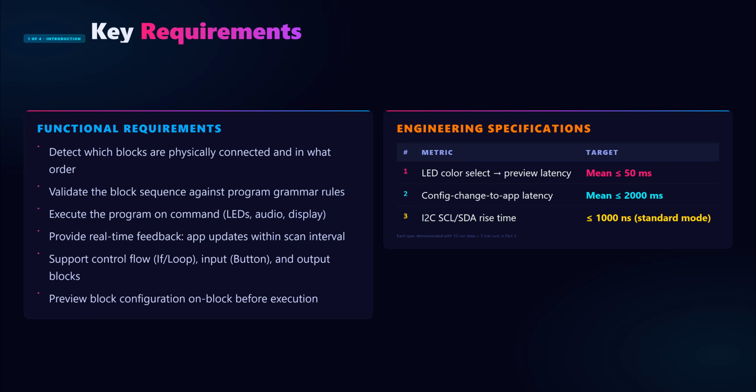Secondly, on the engineering side, we defined 3 quantitative specs that we'll show today. LED color preview latency under 50 milliseconds, config change to app latency under 2 seconds, and I2C rise time under 1,000 nanoseconds. We will walk through the results of the specs later in the demo.